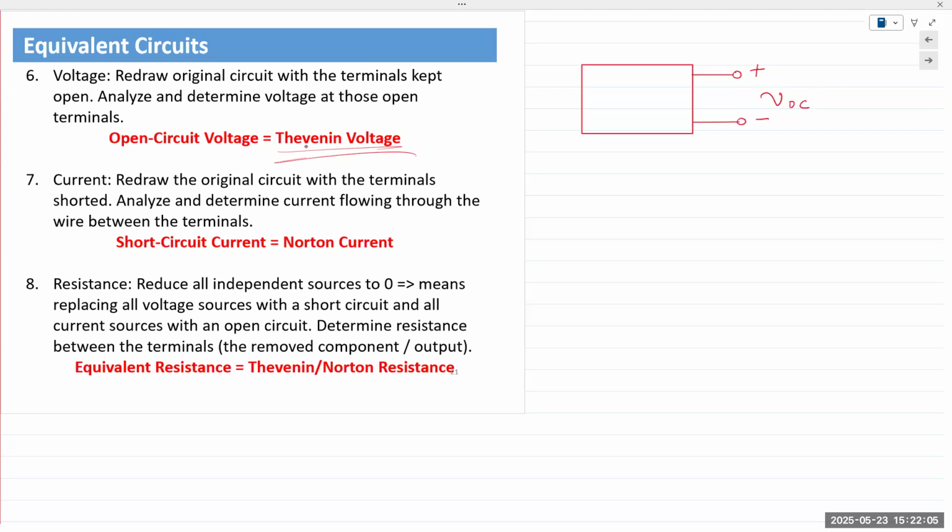In real life, if this was a procedure in the lab, have you all done this procedure in the lab? Thevenin? Perhaps not. In the lab, it is as simple as simply taking the 2 terminals and measuring the voltage. That's it, like a 5-second job.